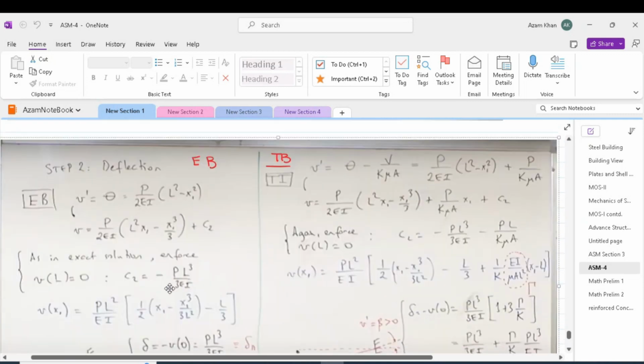In most structural software, we can have an option for either using Euler-Bernoulli beam element or a Timoshenko beam element. So we have to use our engineering judgment whether shear can be appreciable to an extent that the vertical fiber of the beam won't be perpendicular to the elastic curve, or flexure influence is significant, in which case the vertical fiber of the beam will be perpendicular to the elastic curve.